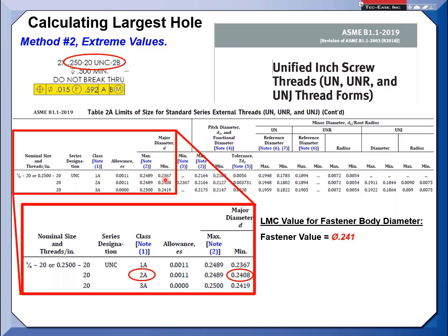Now this is the bolt, but then the bolt's fitting in an internal thread, and depending upon the class fit, that's the slop. But once you start torquing those two features, they'll try to self-center.